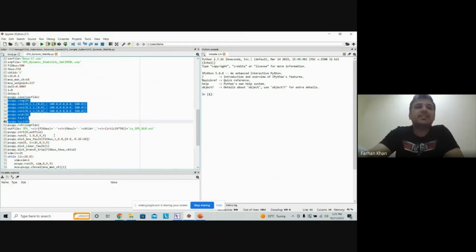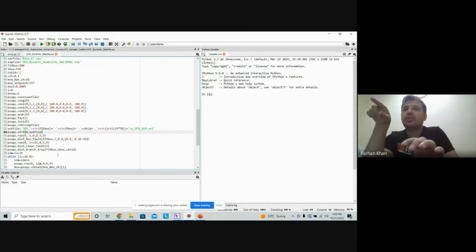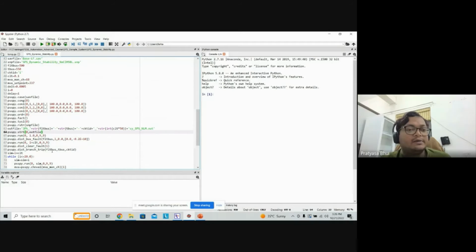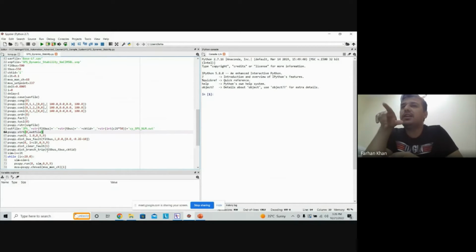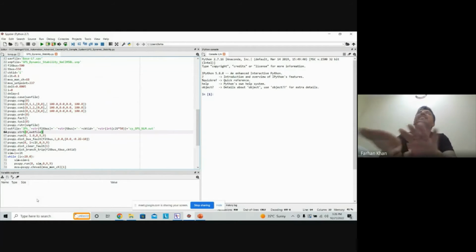Moving on, then psspy.start with the out file. So what exactly is this command doing for you? This command is going to initialize your case. When you're performing these simulations manually, you click on initialize prior to performing simulations, right? So you make your simulation ready and initialize all your components or channels at t equal to 0. So this is exactly what is happening with this command. And then psspy.run. So I am running the simulation for 1 second in steady state.